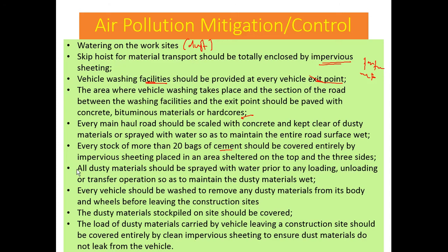All dust matter should be sprayed with water. So all this mitigation action can be used to reduce or control the total particulate matter. Everything should be washed to remove any dust before leaving the construction site. So it is important to provide the vehicle washing facility.